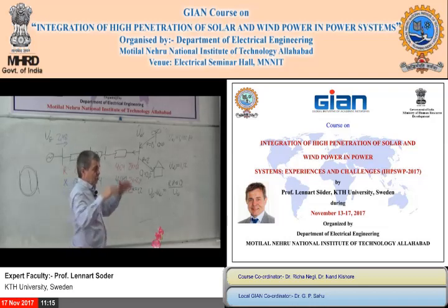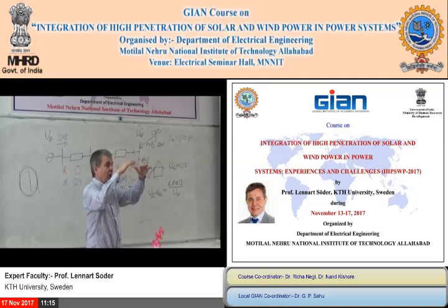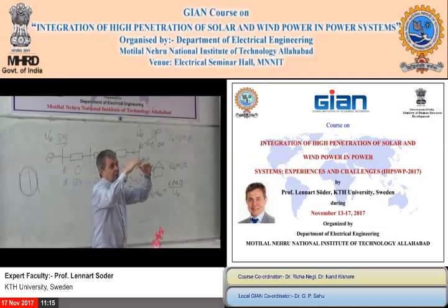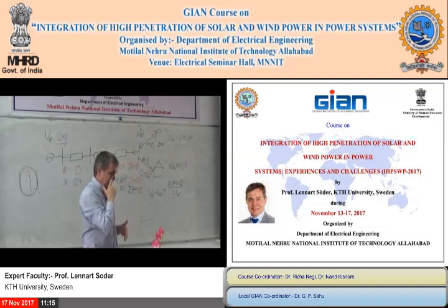And then you have the other issue, which is coming more and more as you have more of that technology today. If this is the maximum, you can, of course, operate slightly lower. But then the question is, why should you? Why shouldn't I use all the energy in the wind? Why shouldn't I use all the energy in the solar? It's more or less stupid to not use everything you can. But in an extreme situation, or if you have an extreme surplus, you can decrease. And then if you are decreasing the production in solar and wind power, you can have primary control in both directions. If you're on the maximum, you can only decrease. If you are lower than maximum, you can go in both directions.